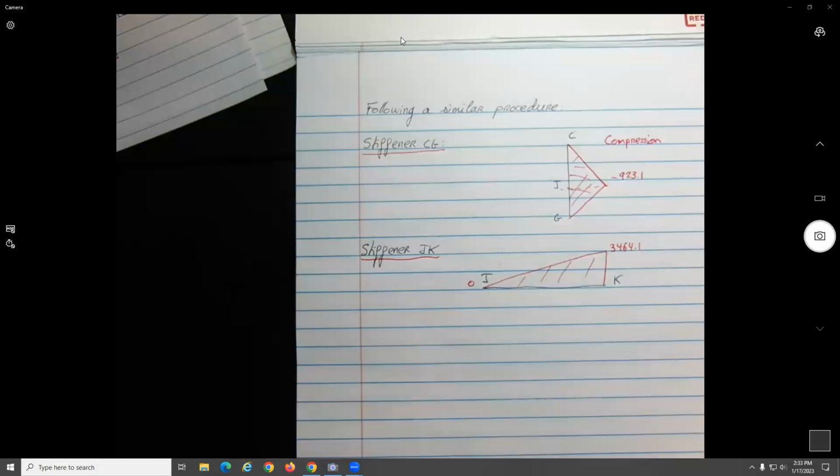Force divided by height. Does that make sense? Okay. And if you look at this, what should be the 2 members that really will be resisting this load? This one and this one, no? In our approximation, we assume this one and this one will not resist anything. However, the load here, the shear flow that will be transmitted over here, will then be transferred within the panel this way, no? Yeah, does that make sense?